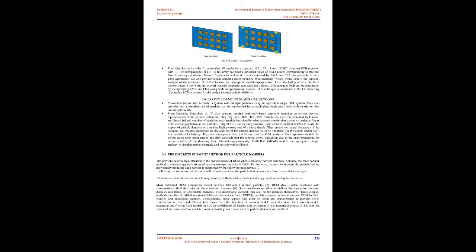3.0 Particle damping numerical methods. Yokomichi et al. 4 are able to model a system with multiple particles using an equivalent single DOF system. They also consider that a complete bed of particles can be represented by an equivalent single mass body without friction that collides plastically. Das et al. Elmqvist et al. 5 also presents another multi-body-based approach focusing on correct physical representation of the particle collisions.